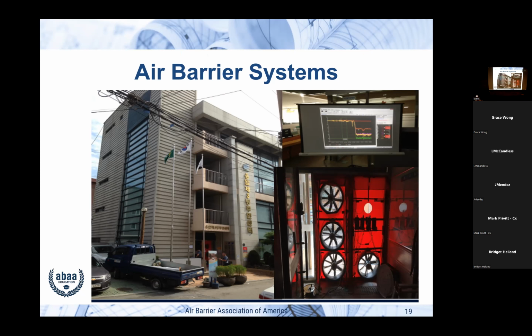Remember, I said it was 10 years ago. When we tested it, it was actually flipped. Even though we had a big hole, I'm going to say about 30 inches in diameter of a duct going out, they had done a lot of things to reduce the unintended airflow. That was actually a pretty tight floor. The top floor leaked like a sieve. Now we understand why, because nobody cares about the roof. We don't tie it into the walls and so on and so forth. But it was the whole thing that we did then and we want to do now here.